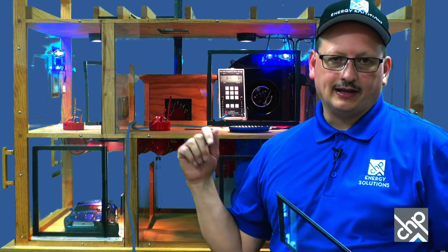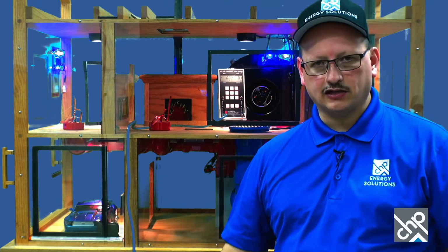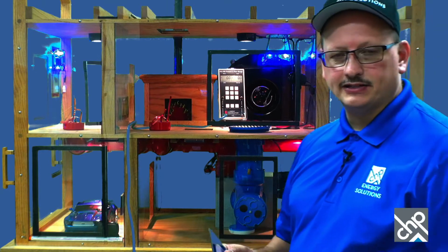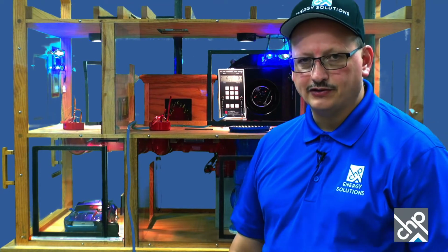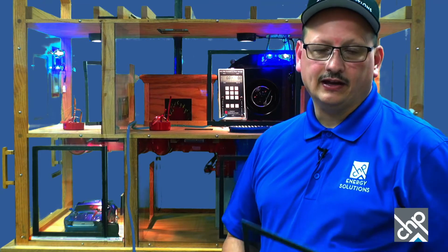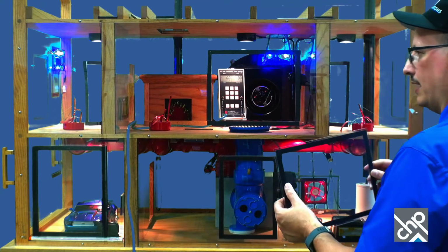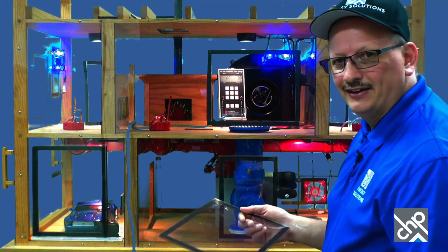And we'll probably get to do a quick scenario like that. What we're doing here is just putting the pieces together. So this just shows you how exhaust fans can affect the pressure in the building, and maybe combustion appliances if you have those. If you've got an all electric house, that's good as far as smoke going out the chimney. You may have some issues if you've got an attached garage, or a humid climate, where you might be bringing in excessive moisture. So pressures can still be an issue even in houses that don't have combustion appliances, if you've got other issues in the house. Of course, car exhaust would be a combustion appliance.